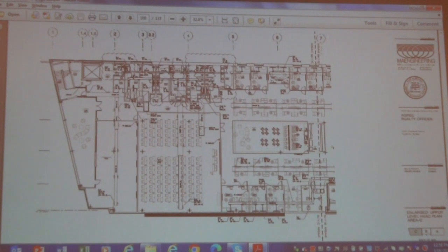In this area here, they call this office space with all those chairs. And they said this is office space, so there's only 5 people per 1,000 square feet in there. Well, obviously you can see that that is not true. So I went back to them and said, no, you're using the wrong table, because that office in the ventilation code has to do actually with individual offices.